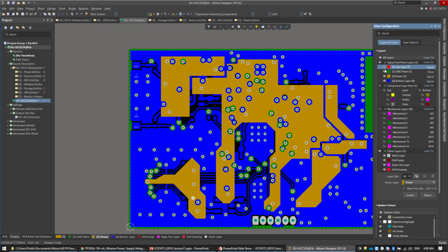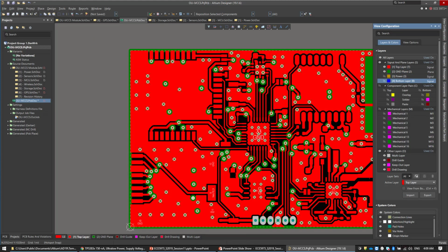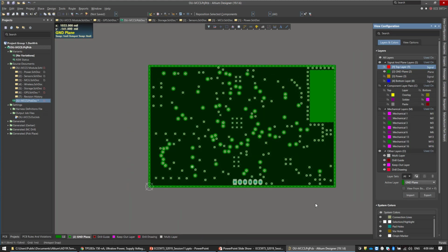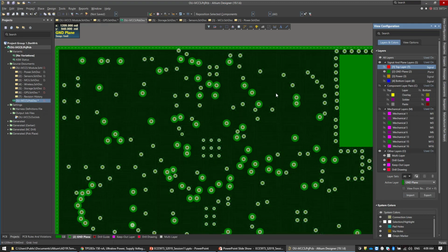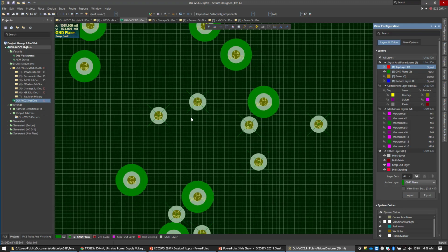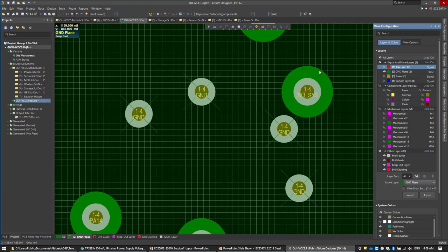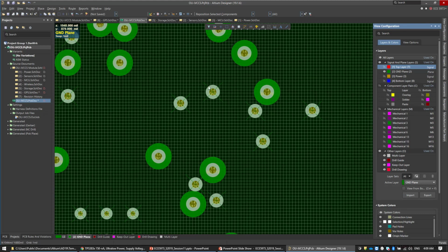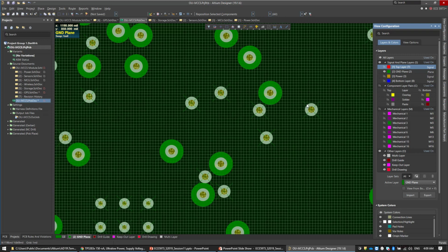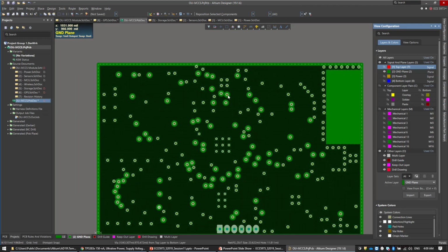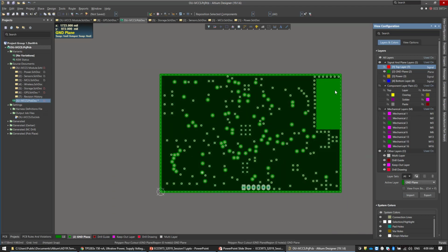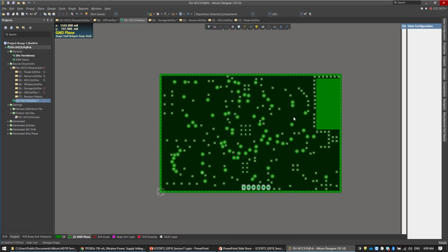So let's take a look now at the ground. Now the ground is a plane. Everything is ground in here. And these are not connected because this is negative now, because this is a plane. Here they are connected. This ground, you can see these X's. Every X is connected to the plane, and everything that has solder mask around it, these are not connected. And here it's not filled. There is nothing at all in this layer.